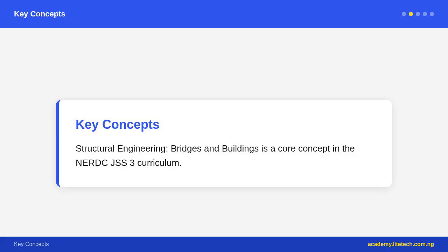3. Truss bridge, uses a framework of triangular units, or trusses, to support the bridge deck. Triangles are the most stable geometric shape, cannot be deformed without changing the length of a member. Members experience either tension or compression only, no bending. Efficient for long spans.